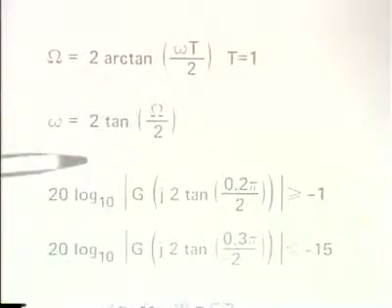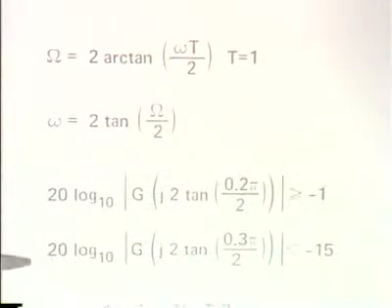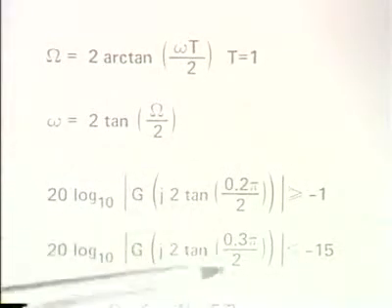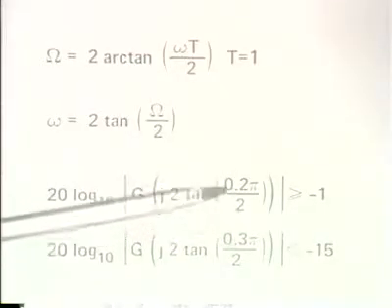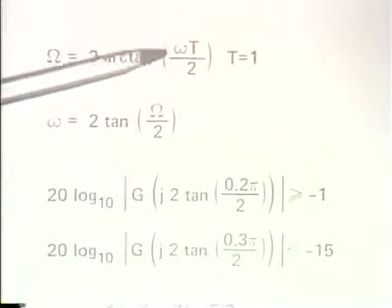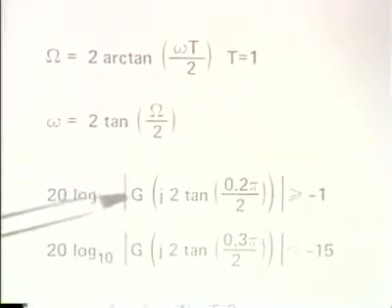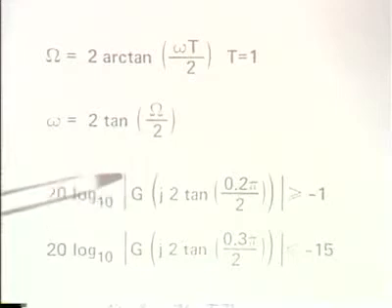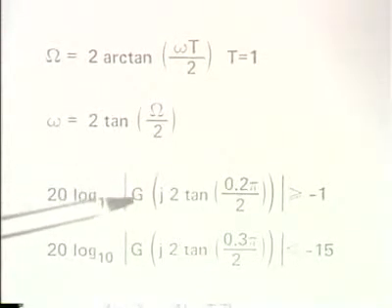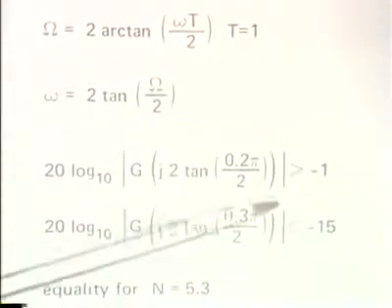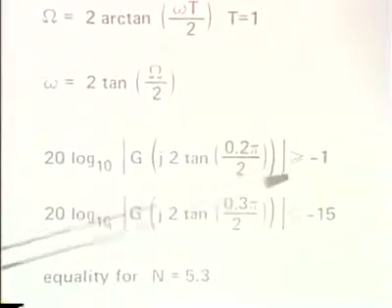So that means then that the specifications on our continuous time filter are given by this. Essentially, passband and stopband edges warped through this nonlinear curve. And I'm using capital G here to denote the system function for the resulting continuous time filter. And so now we could think of designing a Butterworth filter that exactly meets these specifications.